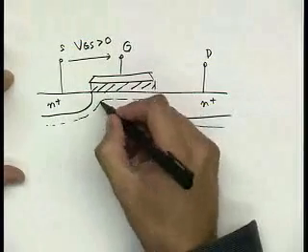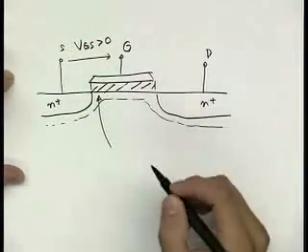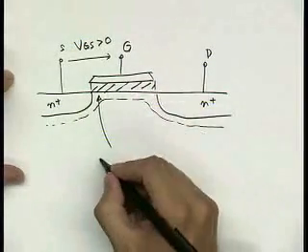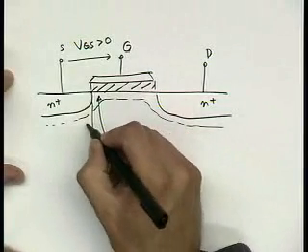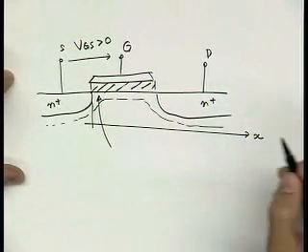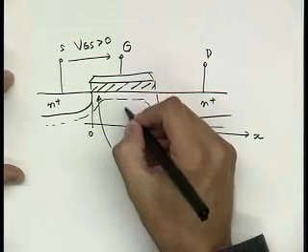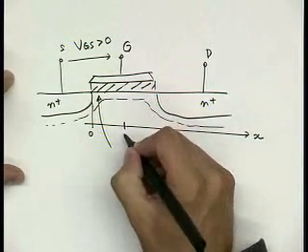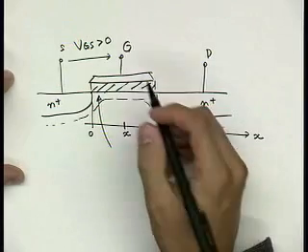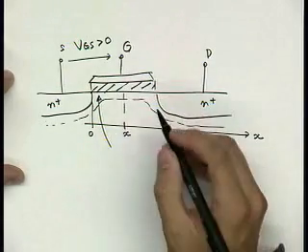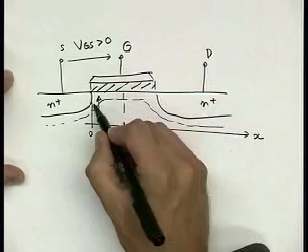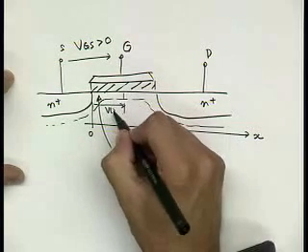So now the amount of charge that you find accumulated under the channel at some point x, if we introduce this as an x-axis with origin over here, and if you look at some point over here x, so then you have potential over here, it's V of x.